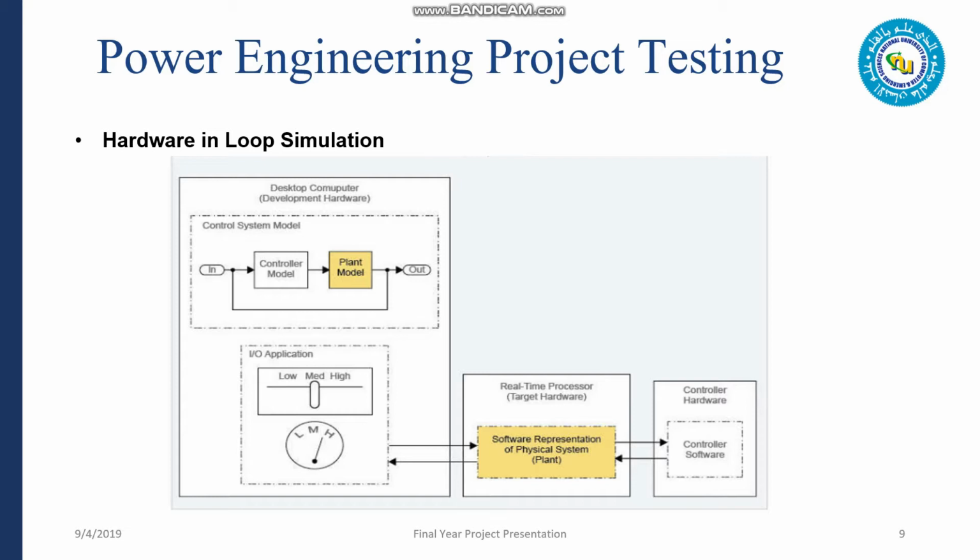When performing HIL simulation, the physical plant is replaced by a precisely equivalent computer model running in real time on a simulator appropriately equipped with inputs and outputs capable of interfacing with control systems and other equipment. In this way, the HIL simulator can accurately reproduce the plant and its dynamics together with sensors and actuators, providing comprehensive closed loop testing without the need for testing on real systems.